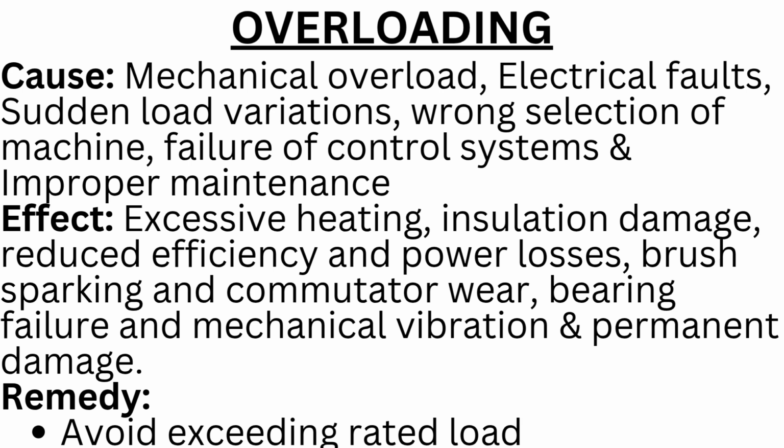Cause. Mechanical overload, electrical faults, sudden load variations, wrong selection of machine, failure of control systems and improper maintenance. Effect. Excessive heating, insulation damage, reduced efficiency and power losses, brush sparking and commutator wear, bearing failure and mechanical vibration and permanent damage. Remedy. Avoid exceeding rated load.